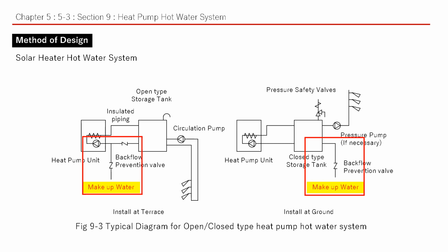Makeup water point is also different. And also a backflow prevention valve should be installed before connecting the hot water line.